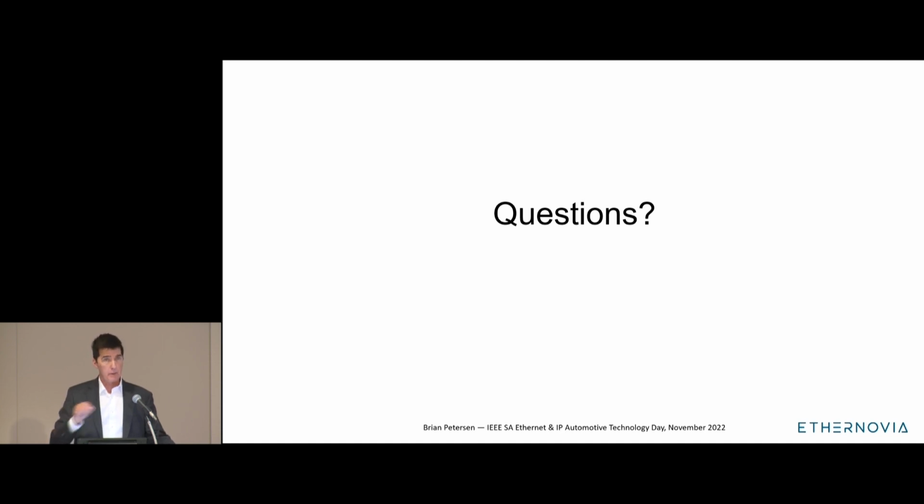Right, but if I'm understanding your question, my intent in this suggestion is that we're replacing everything with Ethernet. So all of the interfaces between ECUs, whether it's a simple sensor or a zonal ECU or a controlling ECU, everything is communicating via Ethernet. So all of the gateway functions can go away. Okay, thank you.